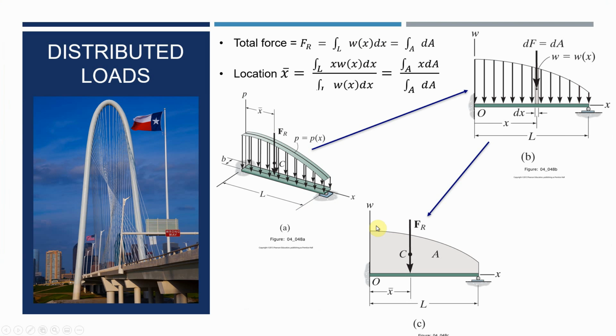Okay. Next topic: distributed loads. They're all parallel forces, you'll notice. We have what's called a loading curve, this w of x. And you take w of x dx to get the force: dF equals dA. The area under this curve is the total force. Remember calculus, when you do an integration, you're getting the total area. F equals the area under the curve of w versus x.